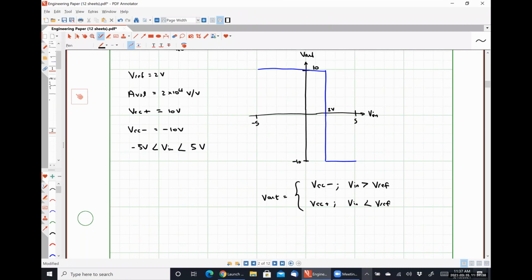And we could create a practical example for whatever reason and go through it, but it's really not terribly important. So this is open loop op amps. This is literally all an open loop op amp can do. It is actually terrible at amplifying a circuit, meaning that you have no control over the amount of amplification whatsoever. That's what those feedback loops do, is put some constraints on being able to control the amount of gain that is applied to your system.